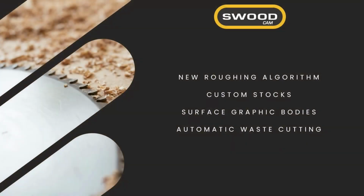Moving on to SWOOD-CAM, we will focus on two main areas: the introduction of new 5-axis features and off-cut machinings. Regarding 5-axis machinings, we have developed a new algorithm for 3D roughing, which includes the ability to define custom stock for 3D rough milling, as well as the option to surface graphic bodies. Lastly, we have introduced machinings that automatically cut the waste into small pieces. So first, the new roughing algorithm.